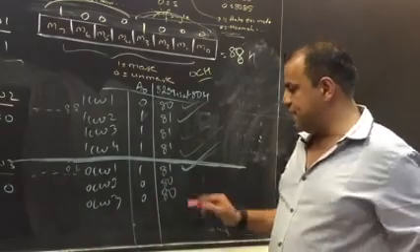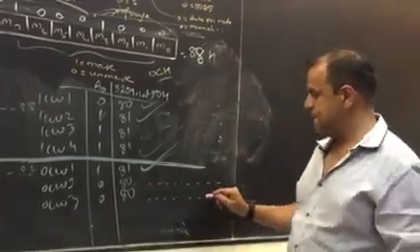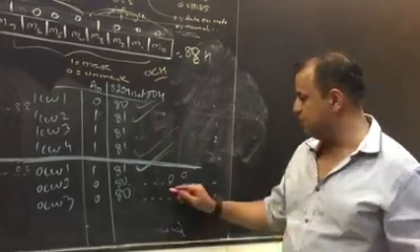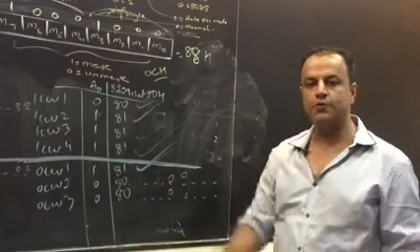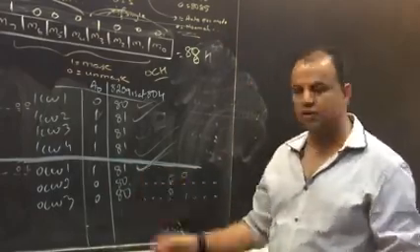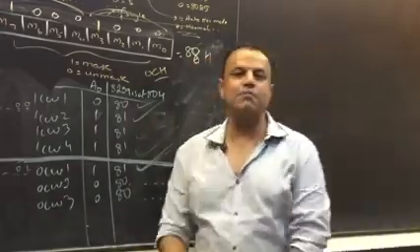Anyway, so any command that comes at the address 80, 8259 looks at the fourth and the fifth bit. If the fourth and the fifth bit are 0, 0, it's OCW2. If they are 0, 1, it's OCW3. Are you clear? So I give you 10 OCW2s, 10 OCW3s, 10 OCW2s, some OCW1s, then OCW2s. It will still know which command is which one. That's how 8259 identifies 7 commands using only 2 addresses.